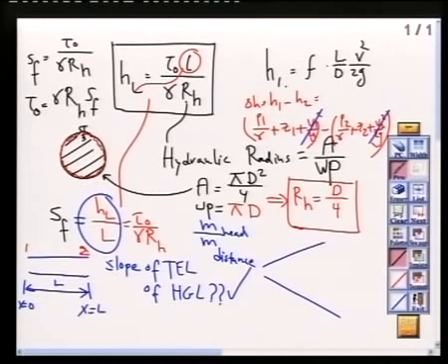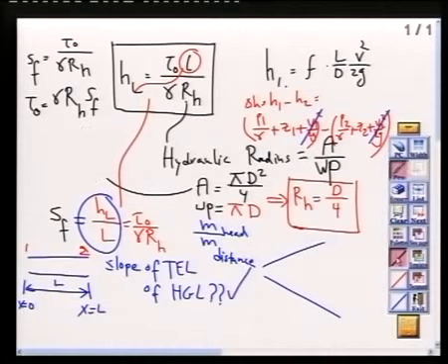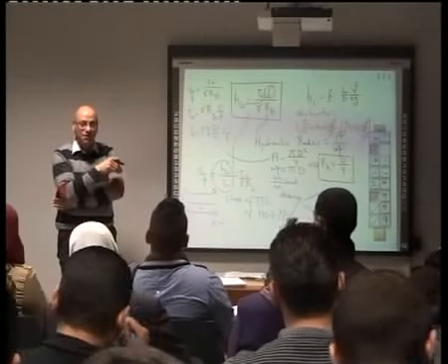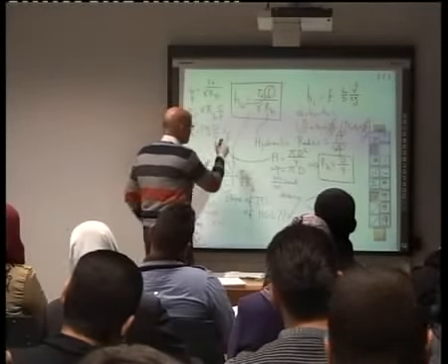Then you can as well make things also, that then tau 0 equals gamma, rho g. This is if we are talking about circular, D over 4. Not only circular, also full flow. Please keep that in mind, because after we finish the pipe flow, we will not really get back to that. All our work will be in partial flow conditions, again, which is more important from a practical point of view than the pressurized situations.